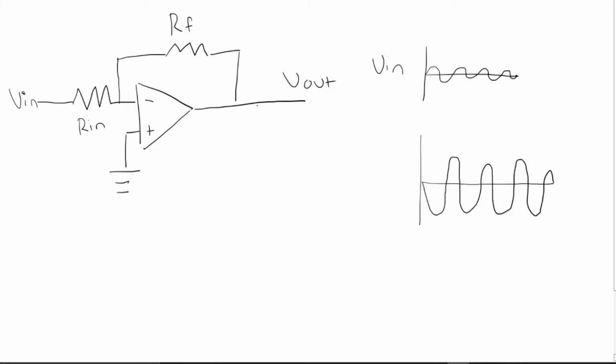Say we may want our op-amp to not just produce full flat voltages, we may want to amplify a signal instead. And here I have an inverting amplifier in this configuration. By having this feedback resistor right here, we can adjust the gain of the op-amp to our liking, and this prevents our op-amp from saturating.